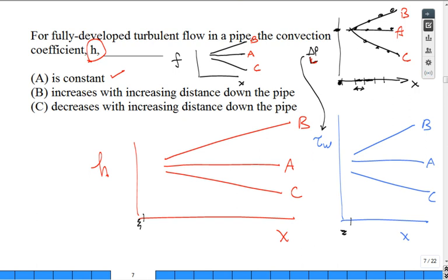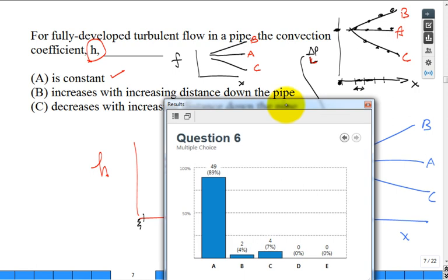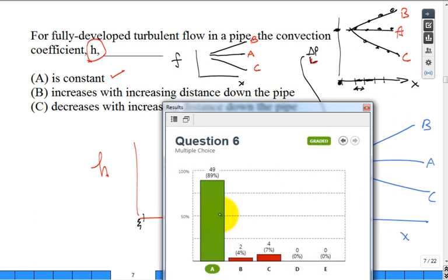So we're going to go ahead and now grade all 4 of these the best I can. The friction factor is going to be constant. It's fully developed. You're not changing the diameter, the viscosity or density of the fluid, or the wall roughness. It's just a constant. And guess what? The pressure loss per unit length, dP over L, per inch, per centimeter, or per foot, is going to be constant, right?